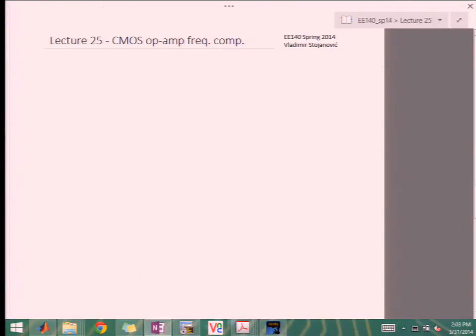If you take a look at the slew rate, to increase it, which is what you want for a faster response, you have to increase I and drop C. Now, again, we add this C in order to compensate the whole amplifier, right? So here you see again a problem. Lowering C, yes, you respond faster, but your amplifier is going to start being less stable. So then you have a fundamental trade-off there.